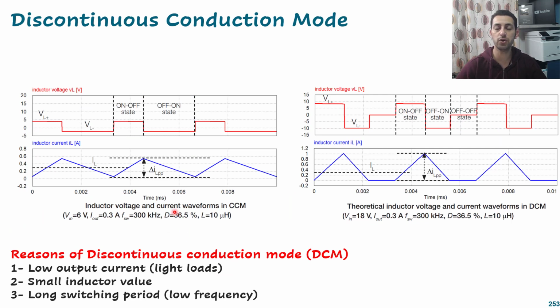But if we see some waveforms, and this is one of the waveforms here for the inductor current, I think we will agree that it's all above 0 and it's always continuous. So there is no 0 current passing through the inductor here. What about the voltage? For the on time, the voltage is always positive and constant. In the off time, the voltage goes negative. So we have, for example, -3, and positive and negative all the time.